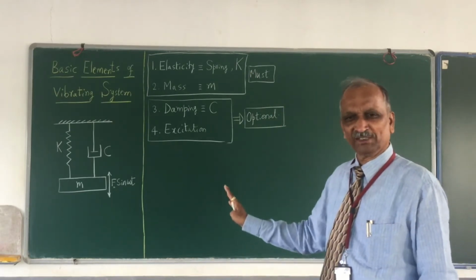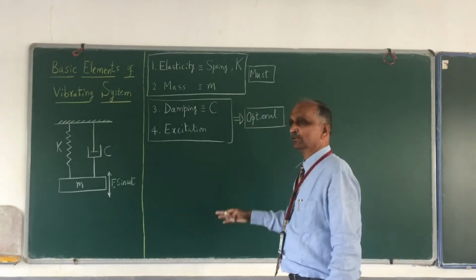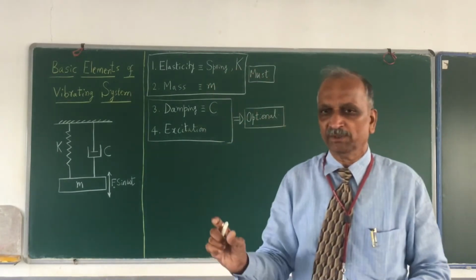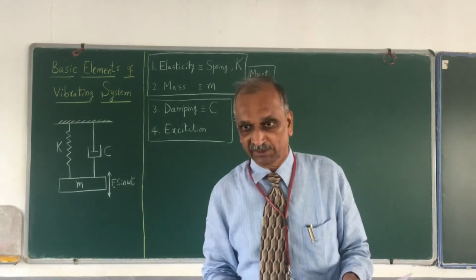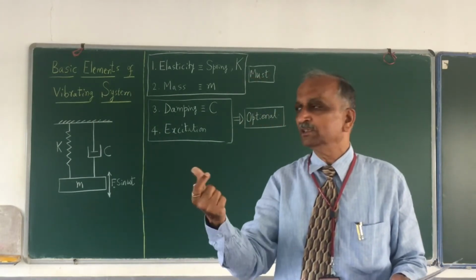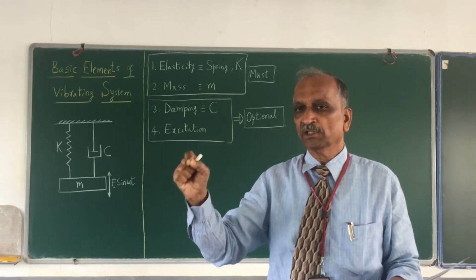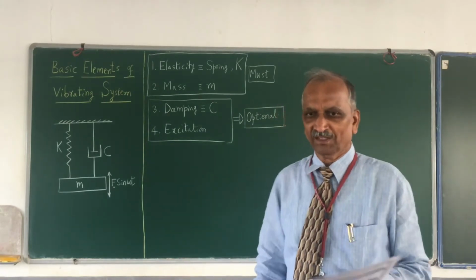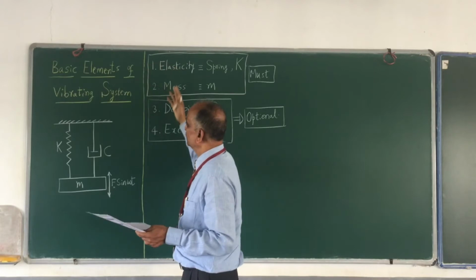The stiffness will remain the same, but instead of force per unit deflection, for this K I shall have torque per unit displacement. Displacement in the case of torque is nothing but the angular displacement, measured in radians. So torque, Newton meter per radian, is the unit for angular stiffness. I shall come to that a little later.